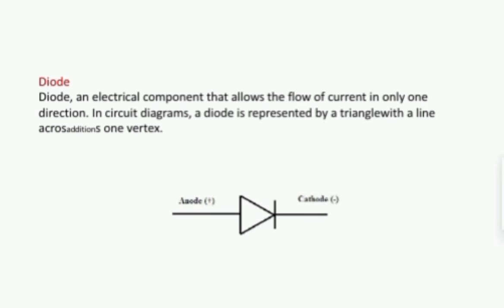The Schottky diode is the same as the PN junction diode except for the forward voltage drop. The forward voltage drop of the Schottky diode is very low, on the order of 0.15 volts to 0.45 volts, when compared to the ordinary PN junction diode, on the order of 0.7 volt to 1.7 volts. Also, the current switching time of the Schottky diode is very small compared to the PN junction diode.